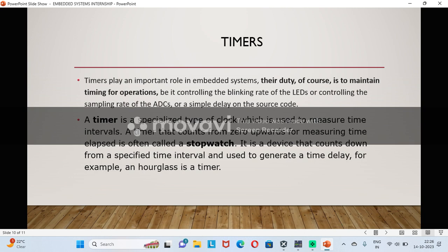While the MCU is executing a program, if there is something that needs immediate attention, an interrupt is generated by that task, the execution of the current program is paused at that time, and the interrupt is handled. So in the example we saw, the mobile is the interrupt and the presentation going on is the execution of the current program. In between, if the mobile rings, we run to the mobile, leaving the presentation. This is a very basic example of an interrupt. The timers run parallel and independent of the CPU at a specific frequency and interact with the CPU by issuing interrupts.